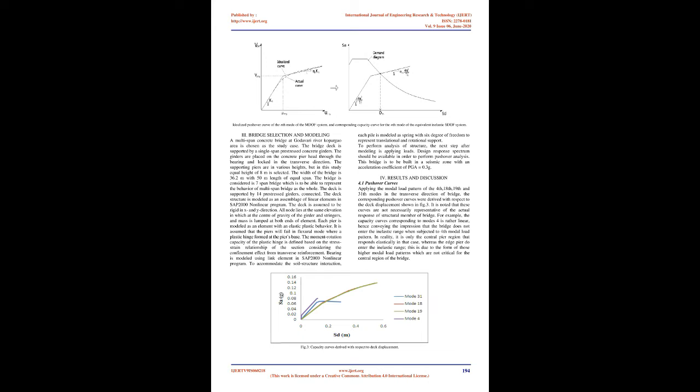One of them is to perform pushover analysis using an invariant lateral force distribution for each mode independently, to consider the contribution of higher modes. The peak responses determined from every mode are combined using square root of sum of squares combinations. This procedure is termed modal pushover analysis, MPA. Chopra and Goyal [1] claimed that as an improved pushover analysis, MPA offers conceptual simplicity but provides superior accuracy compared to the conventional pushover analysis in estimating seismic demands on bridges.